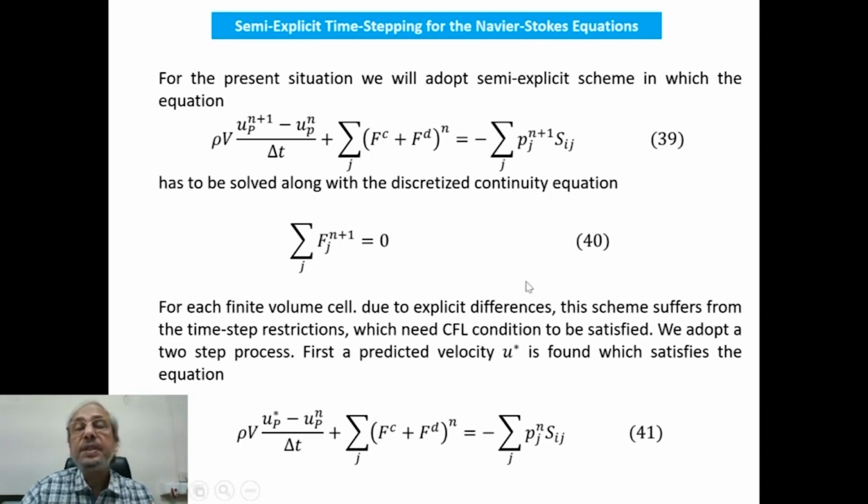If we have to find the velocities in a steady flow problem, we have to progress in the time direction till we get the same values for two consecutive time steps. If the flow is inherently unsteady, then we will have to reach a dynamically steady state condition.